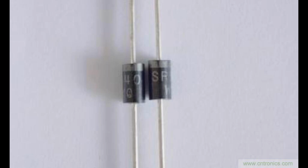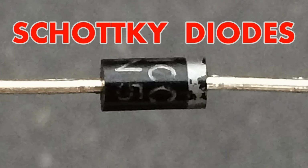It refers to the short time it takes for the diode to switch from its conducting state, forward biased, to its non-conducting state, reverse biased, when the polarity of the voltage across the diode changes from forward to reverse. During forward conduction, majority charge carriers, electrons in N-type and holes in P-type, move across the diode junction, allowing current to flow. When the polarity of the voltage reverses, the diode needs to quickly block the current flow to transition into the reverse biased state.